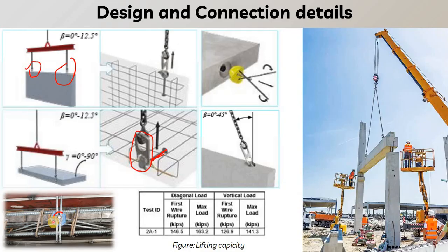And here you can see this is fixed in position before pouring the concrete, and this is the recess former that is used to create the semicircular shape, and in that semicircular shape this kind of lifting clutch is used, and it will be fixed, and then it will be lifted to demold the element.